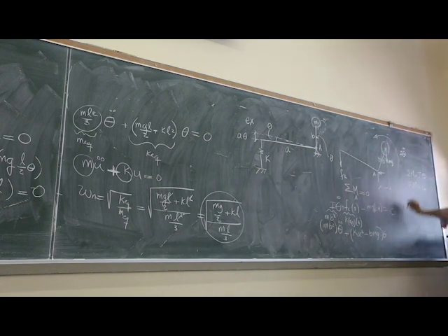The summation of moments becomes 0. So the D'Alembert force, you put it in the opposite direction of motion, so the problem becomes like a static equilibrium. By including the D'Alembert force, you have the dynamic equilibrium, which is analogous to static equilibrium. Sum of forces equal to 0, sum of moments equal to 0. Does it matter if we do it that way? They're identical. In fact, there's a homework problem that asks you to use both Newton's approach and the D'Alembert principle to prove that they are the same.